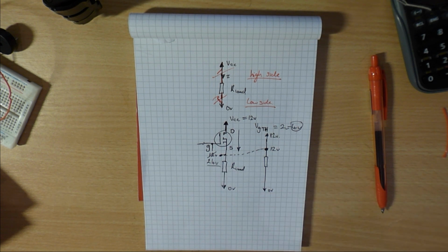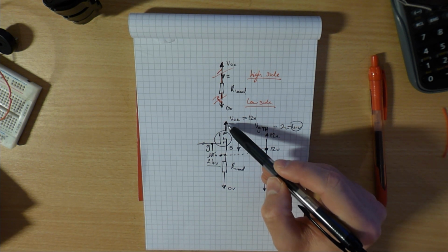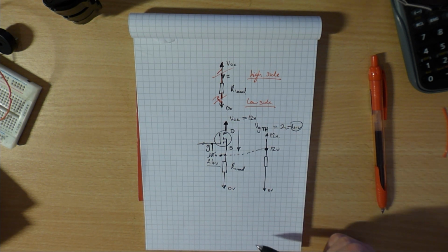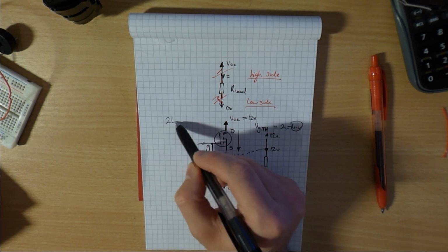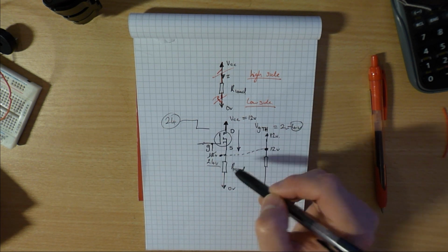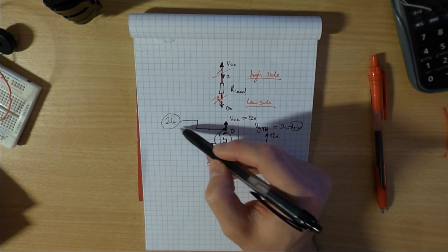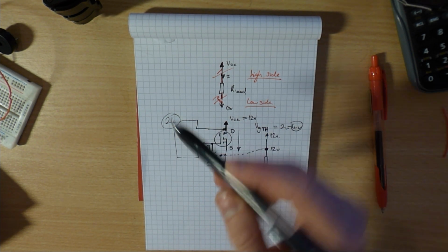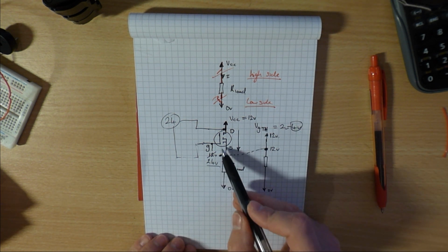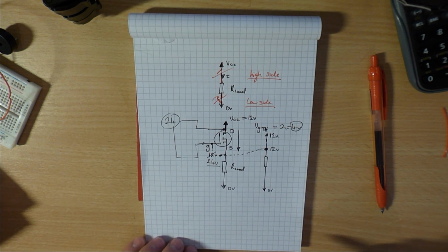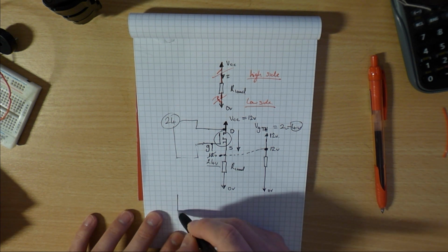And where does 24 volts come from? Usually, for applications like this, the voltage that you're switching at the top here is usually the largest one that you have on your board. If you happen to have 24 volts somewhere else on your board, that's great. You can step that down, and you can use that for your VCC, and then your 24 volts can go and be used to drive the gate. However, if you don't have that, then we need an isolated supply for this, and that's where the gate driver comes in. So if we look at the IR2110,